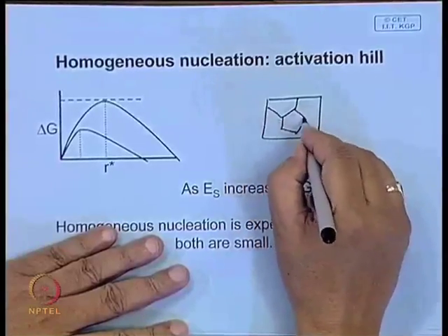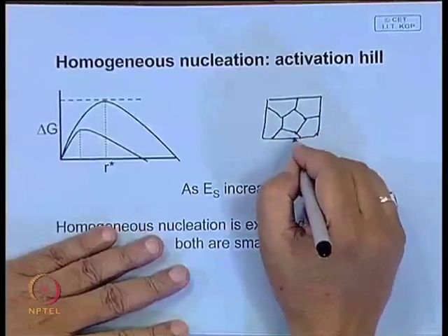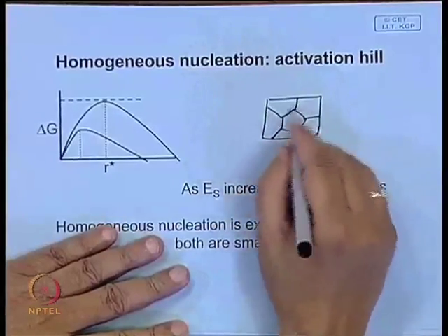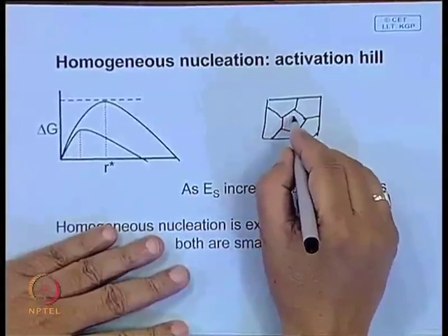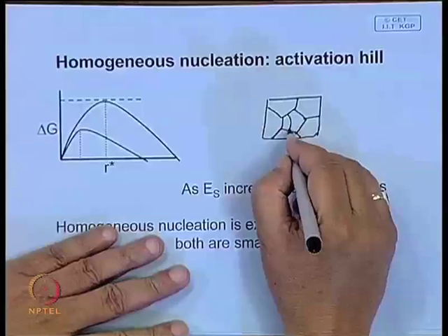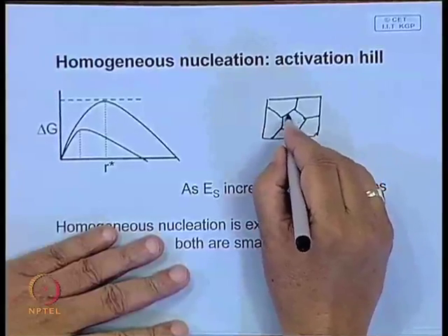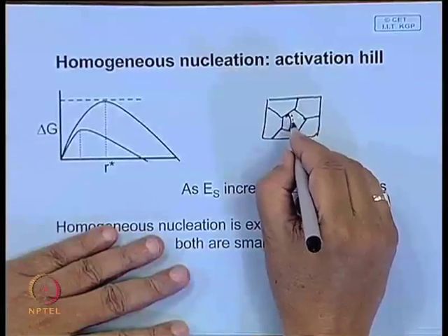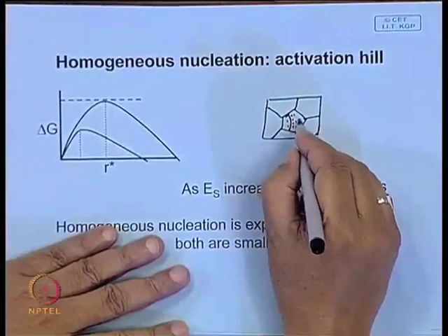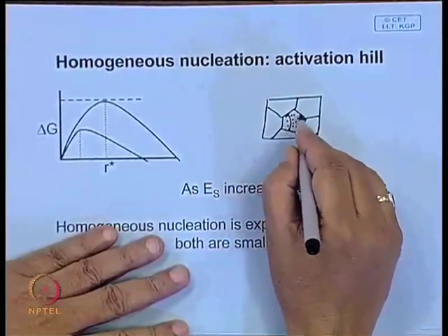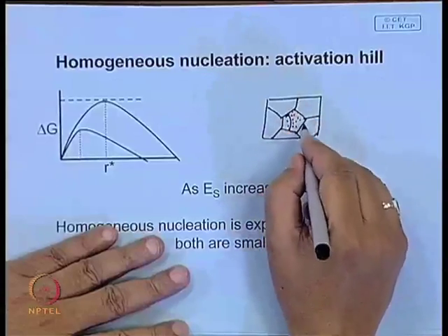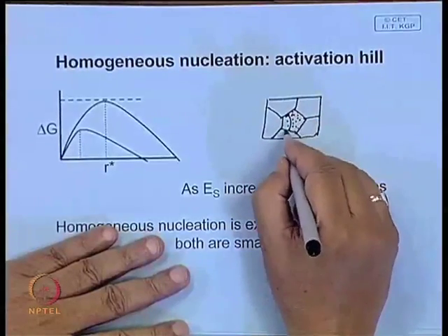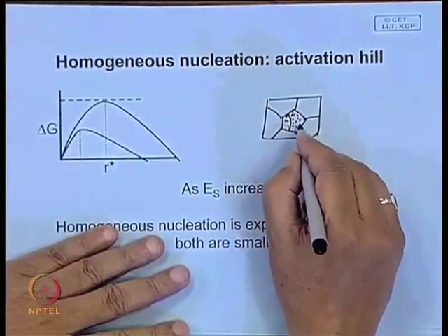you have this grain, and we know that the strength of these grains can be improved if we can make the movement of dislocations through the grain more difficult. So if you have more precipitate within the grain, you need to have not only precipitate in the grain boundary, you need a lot of precipitate within the grain. And how can you get that?